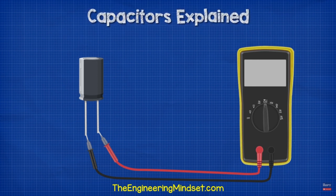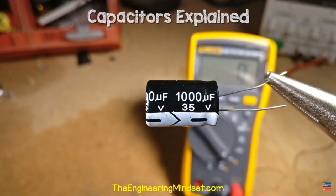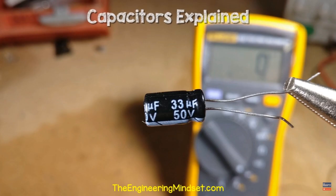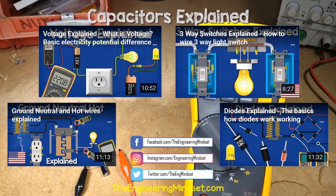We connect the red wire to the positive side and the black wire to the negative side. After a short delay, the meter will give us a reading. We will probably get a reading close to the stated value, but not exact. For example, this one is rated at 1000 microfarads, but when we read it, we get a measurement of around 946. This one is rated at 33 microfarads, but when we measure it, we get around 36.